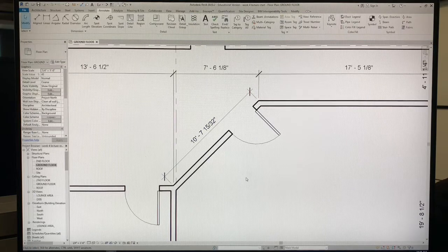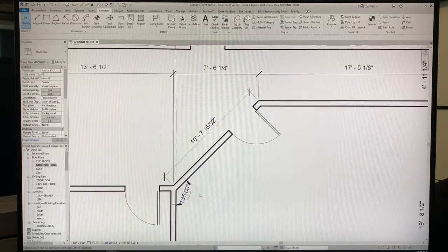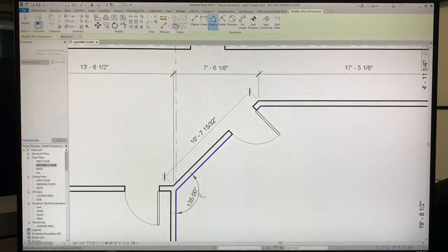Again, now I'm going to have to put the angle on this wall. So let's go now to the angular command. It's like AutoCAD, you just pick the 2 lines that encompass that angle. There's my angle there. You'll notice that when we do angular, there's actually 4 different angles you could choose from. The inside one, the outside one, the acute angles on the sides.